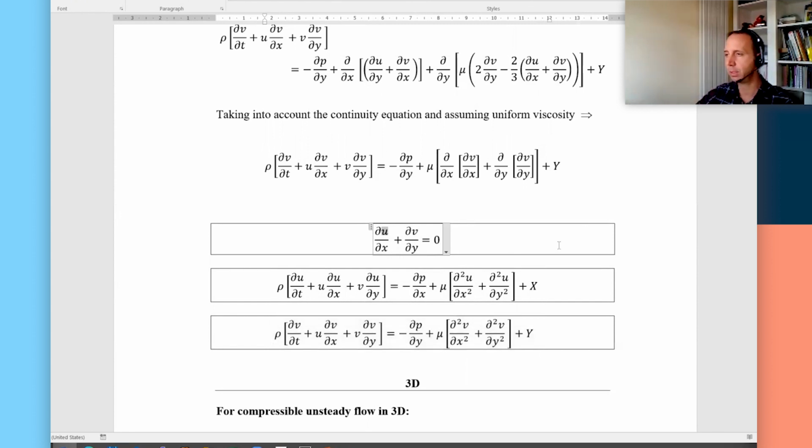What we mean by that is if you were to substitute the values of u, v, and pressure in the equation at every point in space and time, the left-hand side would have to be equal to the right-hand side, all simultaneously. The equations are coupled to mimic the physical coupling between pressure and velocity. Simply, if you change pressure somewhere, it's going to impact velocity elsewhere, and vice versa. So mathematically, you need to make sure all three are solved in a way that satisfies all of them simultaneously. That's the final point.